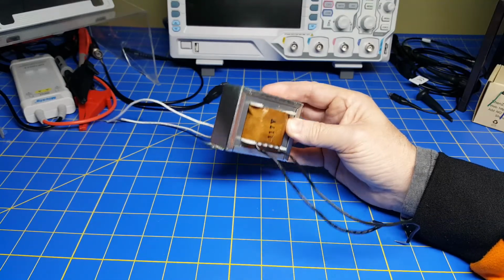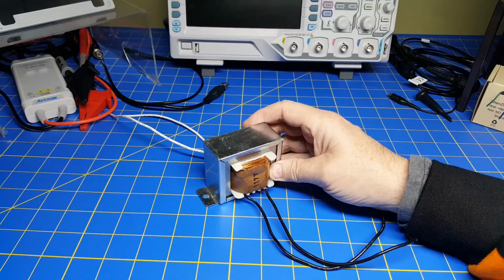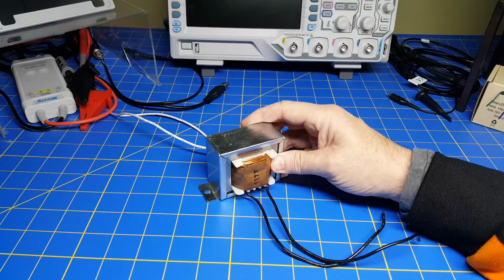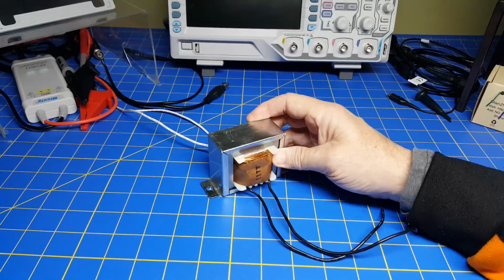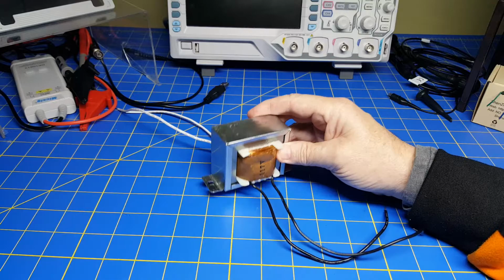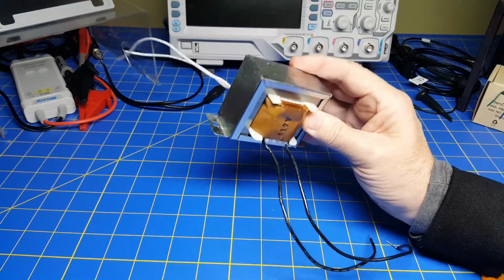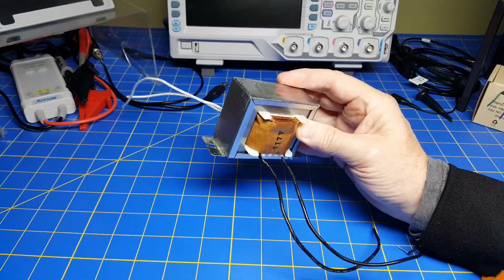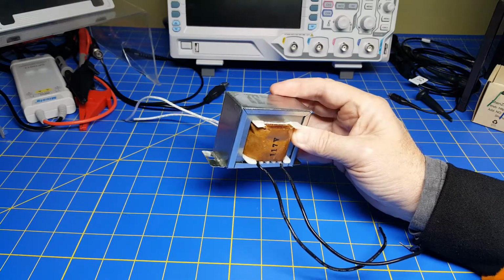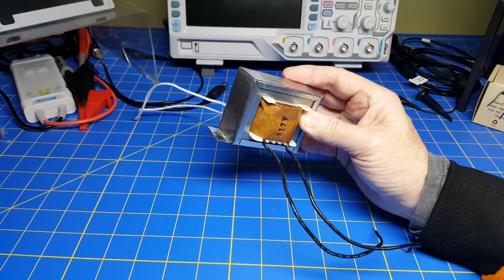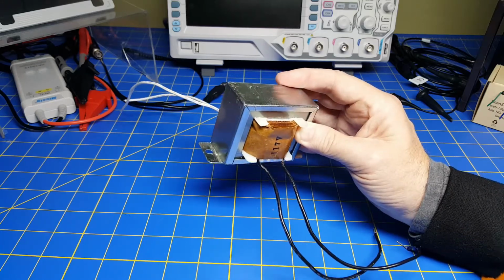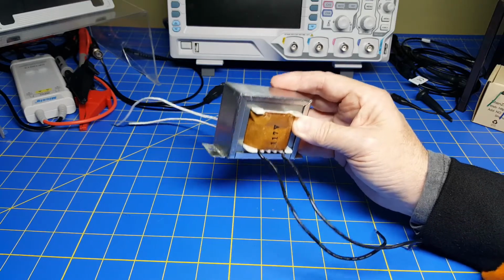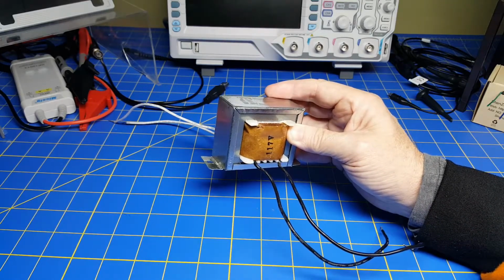Now, the next thing we're going to do, and I consider this a very important engineering approach with just about any engineering problem, is that before you start hooking up test equipment and measuring things, you first learn enough about the piece of equipment that you can figure out what you expect for results, even if it's just a ballpark. For example, we're going to model this as maybe an inductor with some resistances, and we're going to start out by asking what we expect those values to be before we start hooking up our equipment.